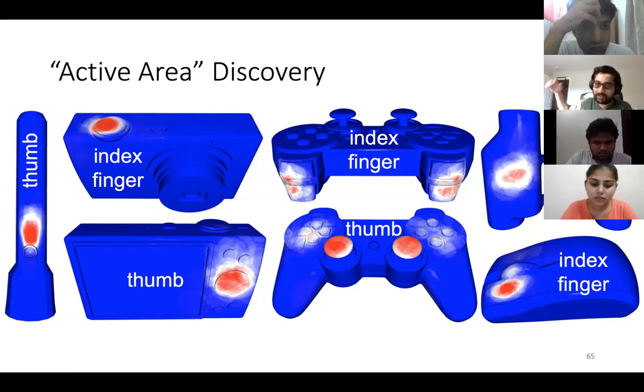Now, if you have a thermal camera looking at the whole room, and you look at data from, let's say, 24 hours or 1 week or something, then these active areas will emerge, based on where people touch more frequently, because those areas will continuously have more and more heat transfer from the hand to the surface. And then if you're able to isolate these active areas, then you know which areas to sanitize more frequently.